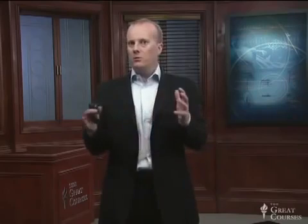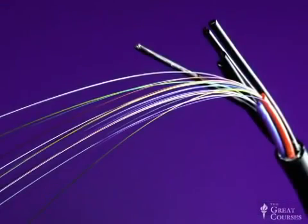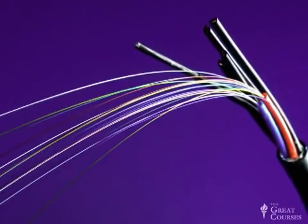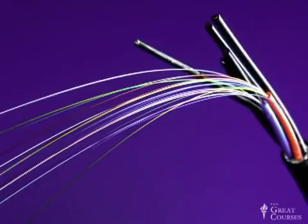Imagine what would happen if light had a couple of options. Imagine if it could bounce at different angles and therefore make it at different rates. Our signal would disperse in time. It would spread out. And that phenomenon is known as dispersion. And if we're going to try to get as much information packed in as possible, we want to modulate our optical source as rapidly as possible. We can't afford any spreading. Spreading in time would be a loss of signal integrity. We would smudge our signal. We would no longer be able to resolve it. And so the design of fiber optic cables that achieve this very low dispersion is one of the central tenets of successful fiber optic communications.